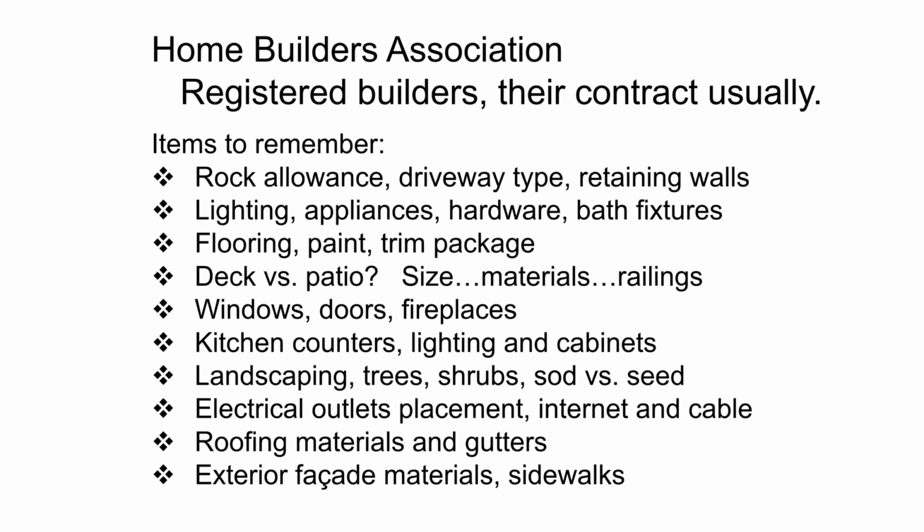Electrical outlet placement. I can't tell you how often I go into houses and the light switches are behind the doors. It's because nobody took the time to actually figure out how they're going to live in the house, that if I want to have this door swing this way, I probably want the light switch over on the right. If I want to have the door swing the other way because I've got a piece of furniture that's going to go on this wall, then I want the light switch placed on this side of the door. So walk through the house, have your buyer visualize where their furniture is going to be placed, and then place your outlets and your light switches accordingly.